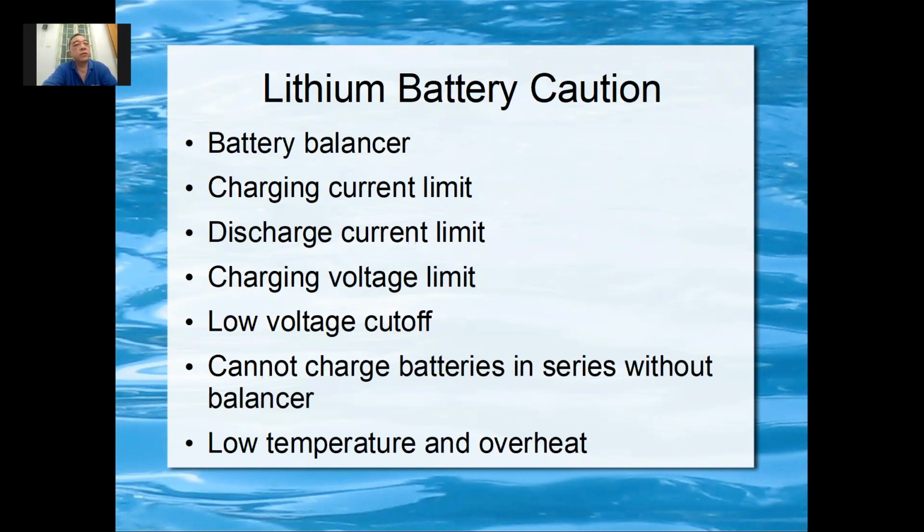So for those, let's say a Tesla car, they put the battery low, zero, is not exactly zero. There's still some energy inside, but they cannot use it. If you continue to use it, you can damage the battery. And your electronics must handle all these things. Okay, so you don't charge the battery in series without a balancer. This one I explained earlier already.